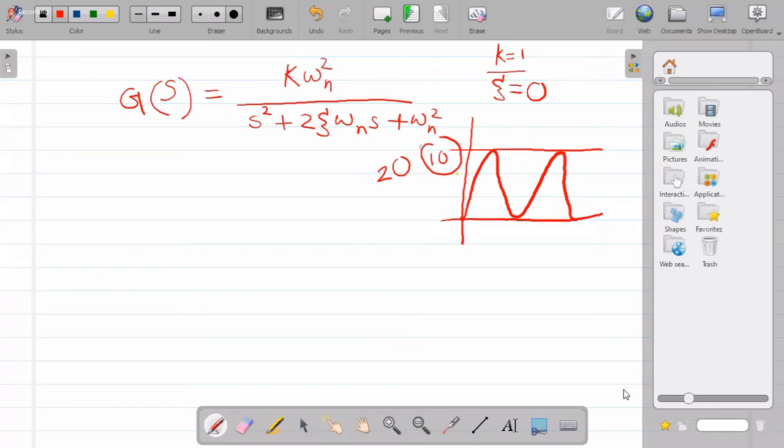Since all the systems are interconnected through these feedbacks, the entire response of the system will not simply be flat top, but completely different, and it will not be what you expect. So what we can do is magnitude scaling. That is, we need to scale down the entire problem so that the range of variation is restricted within the permissible range.